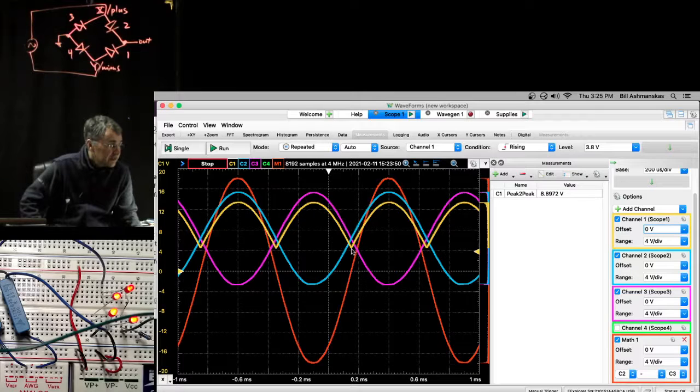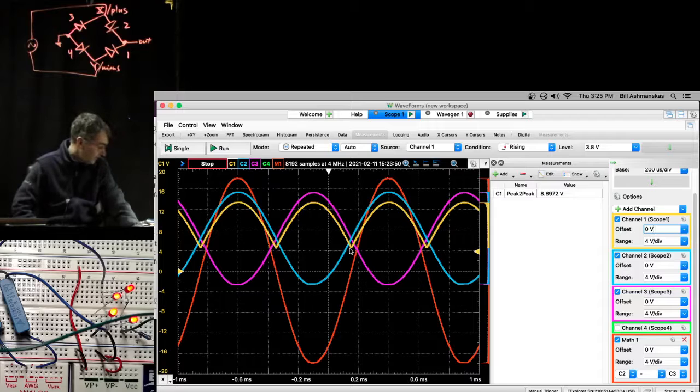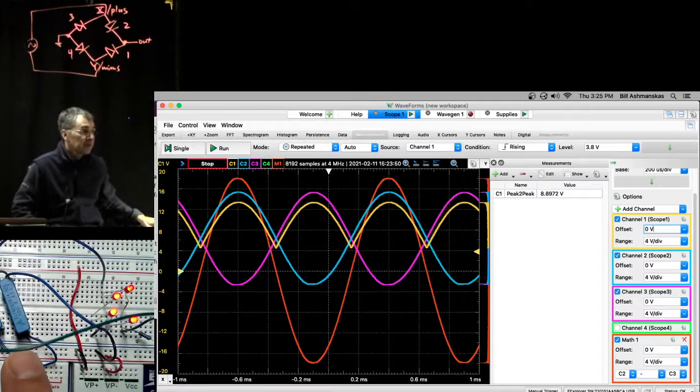And yeah, I don't quite understand that, although come to think of it, maybe the problem is, I thought I was being really clever with these big capacitors here, but one problem with these big capacitors is I don't really provide a DC path for current to flow. So anyway, I'm a little confused about why the yellow curve doesn't get down all the way to 0. But it's still kind of neat.